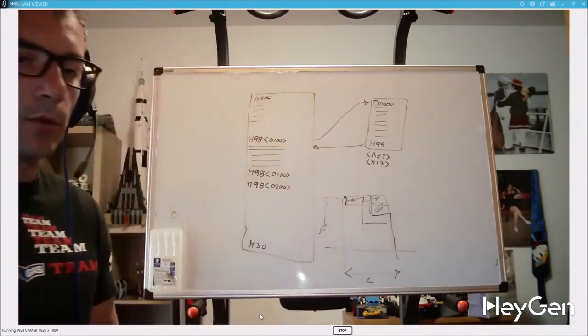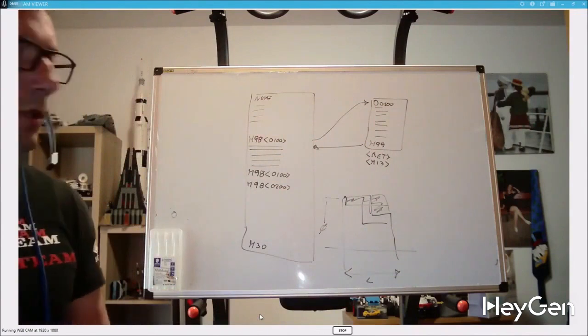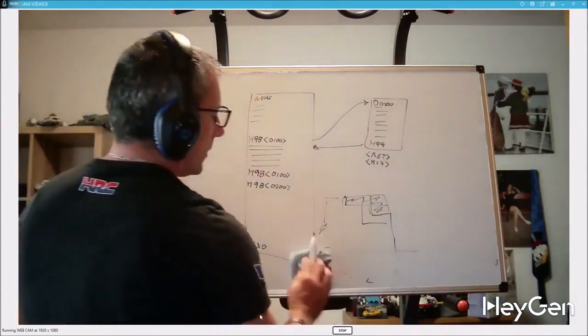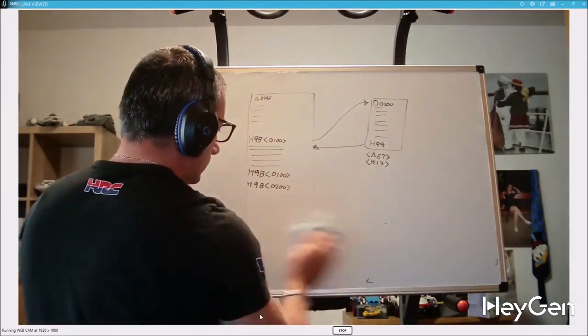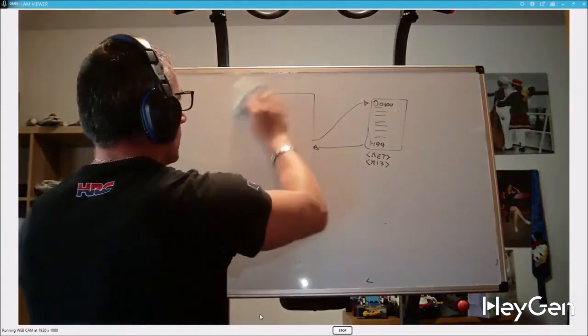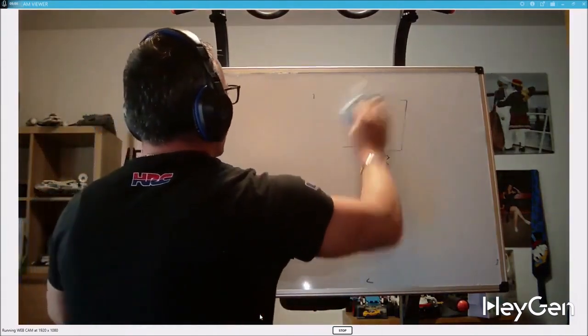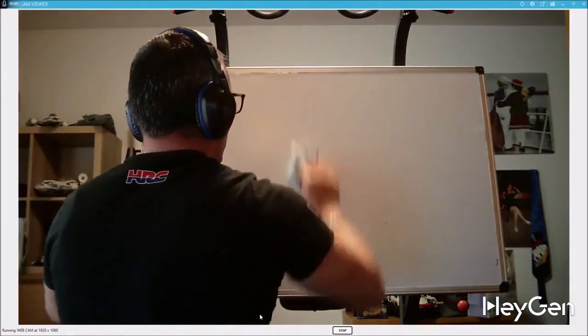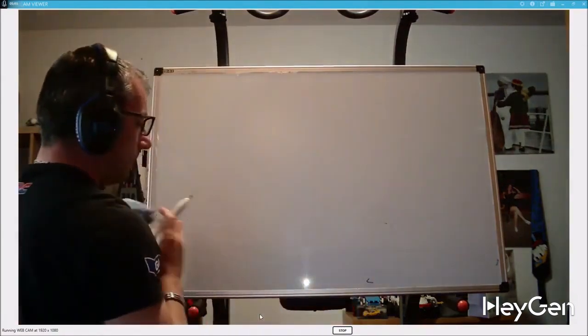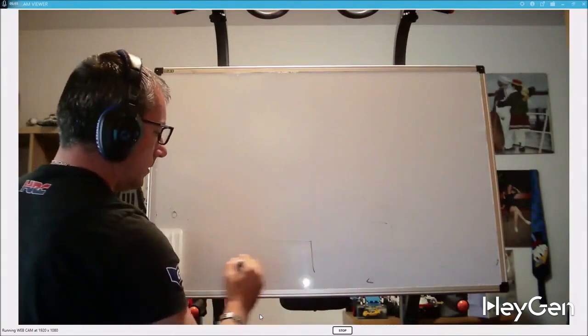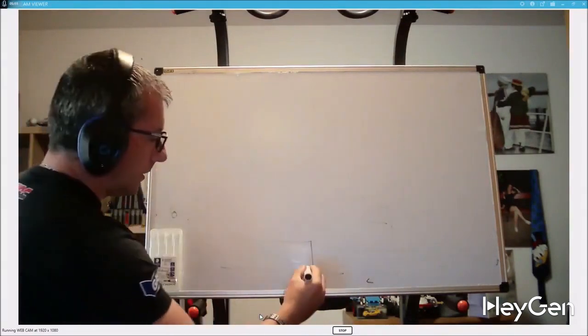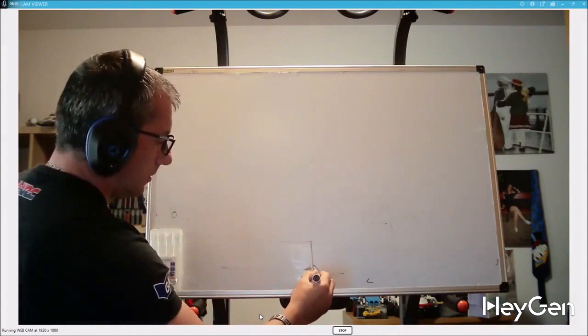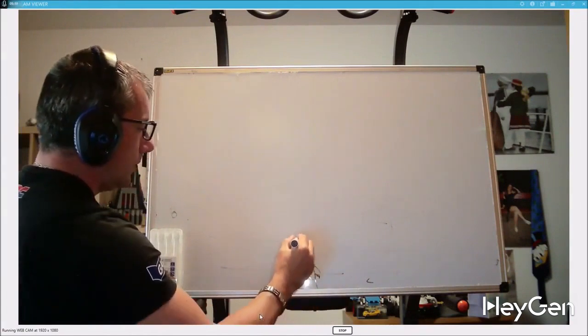So when I have the drawing in hand, I'll call programs 0100, 0200, 0300 within the subprogram. Let's take an example that we'll later see in the simulator. Imagine we have a bar and we need to make a 4mm groove.